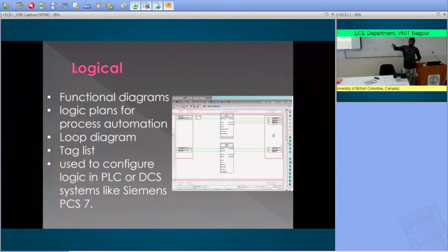So if your sensor is connected to IO tag number 1, there are different types of IOs. In industries they have PLCs which have multiples of IOs. They have 48 IOs. In those 48 IOs, that level sensor will go to which IO number? It will go to the 10th IO or 11th IO. Like that, the wiring details all come under the loop diagrams.